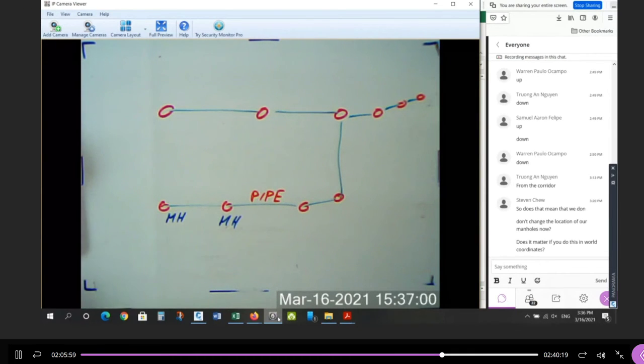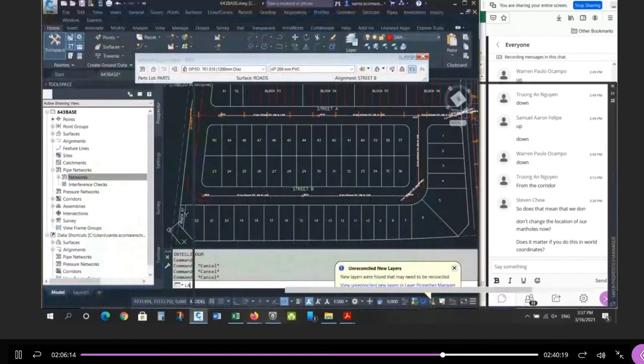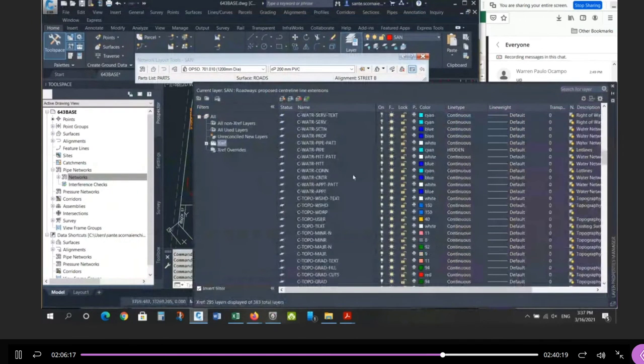Okay, just like last semester. The maintenance hole should be on a layer. The text for the maintenance hole should be on a different layer. The pipes should be on a 3rd layer, and the label for the pipe should be on a 4th layer. And the names of those, I don't remember if they're in the drawing or not, by default they might be. If you go to the layer control, you might see them here. I think they are.